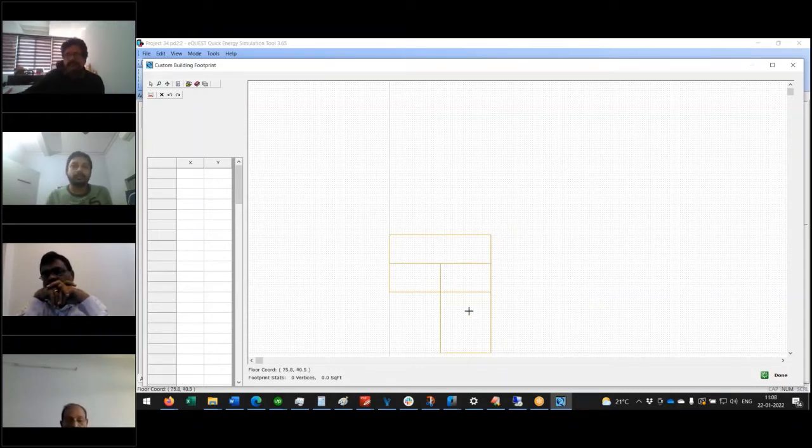But it's always preferable to have a very good common point which is running throughout the building. It will mostly be either stairs or lift or staircase. So either one of these should be moved to 0, 0, and then everything else, like different floors, will always line up in your 3D view. You won't have to worry about it.